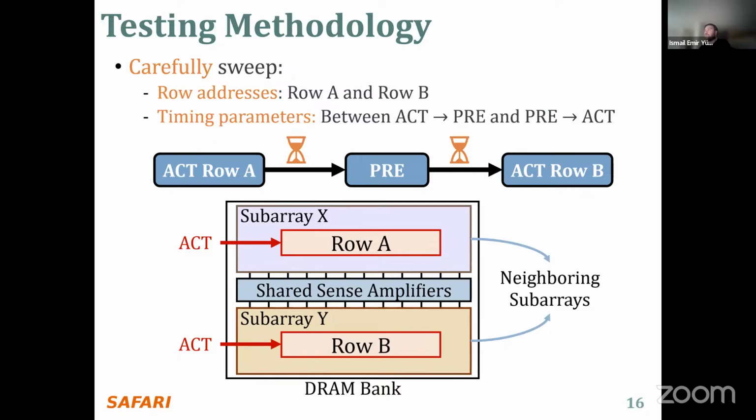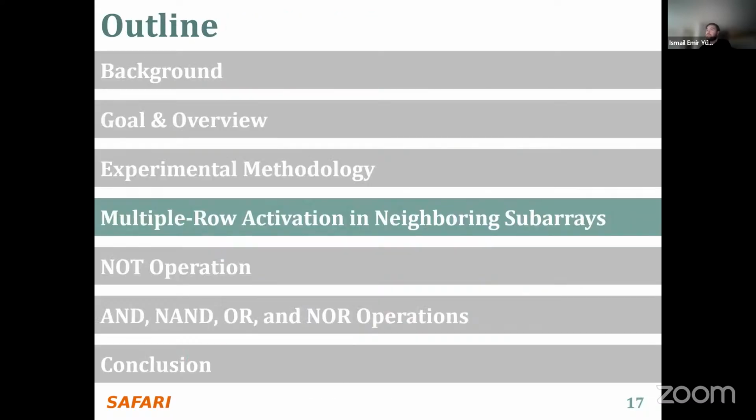And we sweep the timing parameters between activate to precharge and precharge to activate. And now let's look at our first characterization results, multiple row activation in neighboring subarrays.